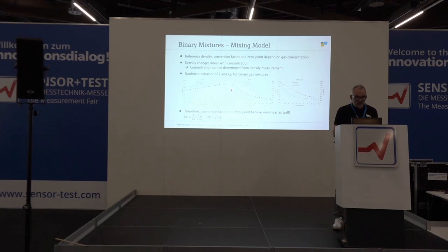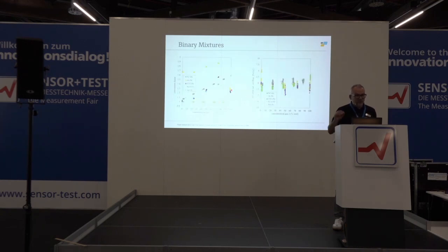So what you have to do is to calibrate once, measure it once for this mixture, and then store it in the sensor. If you know the concentration, you follow this curve and can adjust the conversion factor for these mixtures. And again, if you do this for all these mixtures, you get a quite linear output, which is automatically corrected for all concentrations.